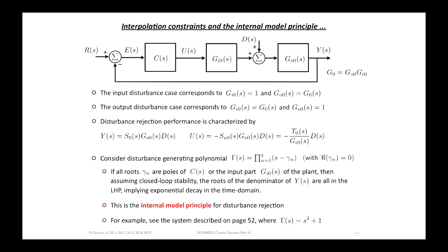So how sensitive this signal is to D is just given by this transfer function here. We might also be interested in how sensitive this signal is to D from the perspective of actuator saturation and rate limits and so forth. And the transfer function from D to here is given by this, where this is just C times this here. And you can re-express it also in terms of the complementary sensitivity function. As an exercise, if you can't see this straight away, go and work it out. We've seen how to get transfer functions from inputs to internal signals lots of times. You just read the equations off the block diagram and manipulate them to find the corresponding relationship.